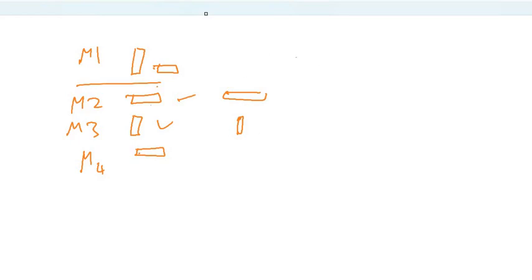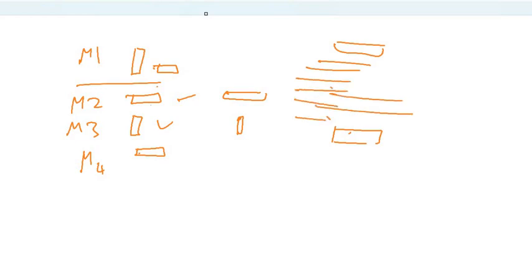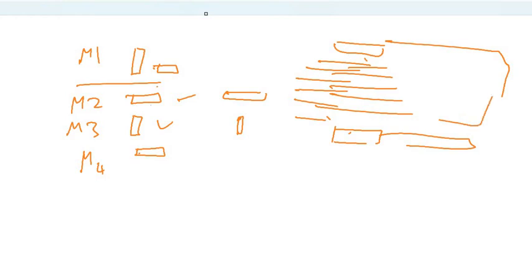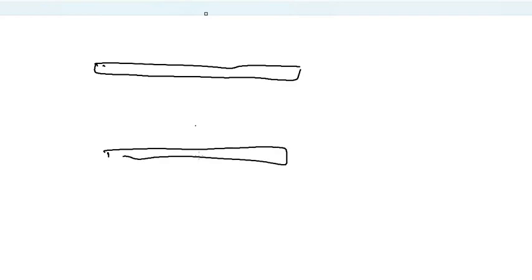It is to avoid routing congestion. Say for example, you've got your gate or a cell, and you've used your M2 tracks here. These are the tracks where you would want to make a connection. Now, for some reason in this module, you ended up using M2 vertically like this. Let me redraw this again. You've got a certain part of your circuit here, PMOS and NMOS. I'm just using a gate as a simple example. You've taken M2, which you have drawn vertically like this, just to make some connection here.